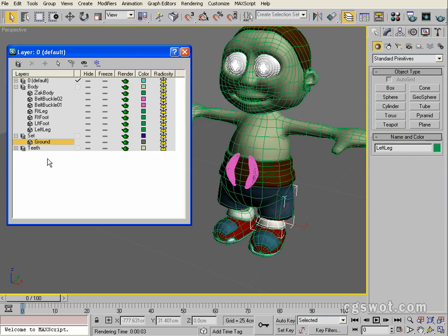If you're going to be doing any materials, especially when reflection and refraction and specularity are so crucial as they are with eyes, it's very important to set up a good light rig, just a simple light rig that's going to give you some of those specular qualities. And that way you'll be able to read how your material is working and how it will work as you move towards a final scene.